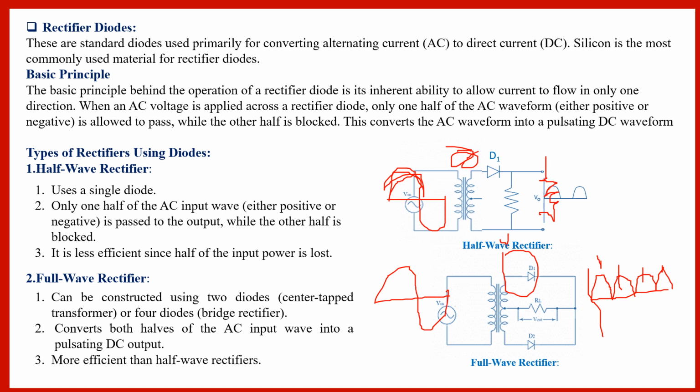That is known as the peak inverse voltage, which comes across the non-conducting diode. If diode D1 has voltage Vm, then for the other non-conducting diode the peak inverse voltage will be equal to 2 Vm. So the diodes must have a high peak inverse voltage in the full wave rectifier, and that becomes a disadvantage for that rectifier.